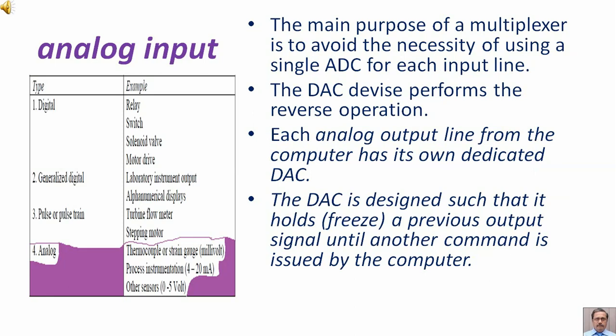Each analog output line from the computer has its own dedicated digital to analog converter. The digital to analog converter is designed such that it holds, that is, freezes, a previous output signal until another command is issued by the computer.